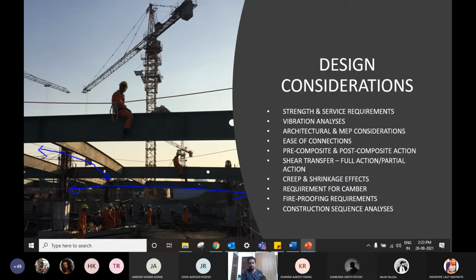For example, in this particular beam, you determine the loads and you design your deck, and you have your beam sizes. It could be like 400 mm total depth. Now that's your strength based design. For the loads that are coming in, you do a bunch of calculations and you say you need only 400 mm depth beams.